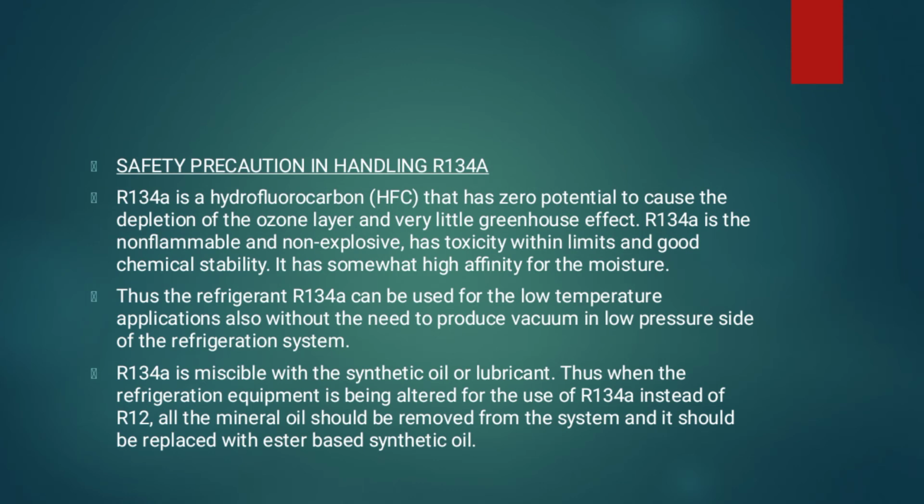It has somehow high affinity for moisture. Thus the refrigerant can be used for low temperature applications, also without the need to produce a vacuum on the low pressure side of the refrigeration system. So this is the downside, or I think the downside of the 134A, since this one is only used in low temperature applications, also without the need to produce a vacuum on the low pressure side. So it is like a plus minus factor.